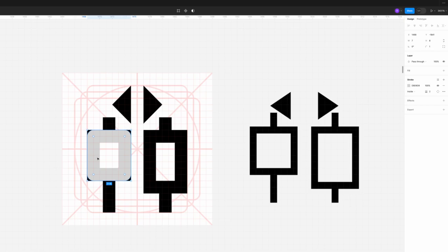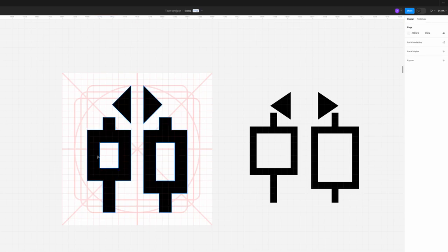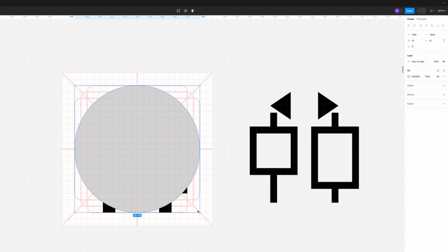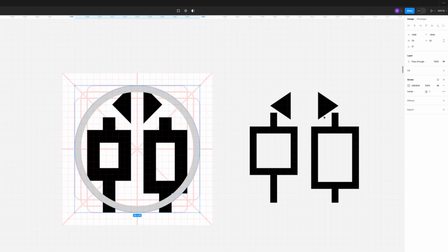Now you can do the same thing with an oval. So for example, let's say I would love to put an oval or a circle all over this graphic here, but I only want the outline. I'm going to do Shift and X, and now I have my outline. I will give it a number 2, and there is my shape.